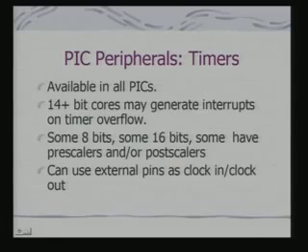Some timers are 8 bits, some are 16 bits, and they have prescalers as well as postscalers. In fact, not all of them have both, some of them have one of them, and some can even have both. And they can use external pins as clock in as well as clock out. So it is not that all these timers are operated by the internal phase clock, the processor clock.